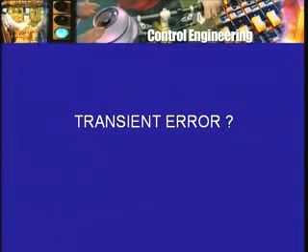So by increasing the gain Ka, I can reduce the steady state error, and so of course I can become ambitious but careless and say that alright, let me increase it by another factor of 10, my steady state error will be still reduced. Well, the answer is yes, but what about the transient error? We have not looked at the transient error at all. We are only looking at the steady state case. What about the transient error? We will see later that if you increase the gain too much, the transient error can be increased.